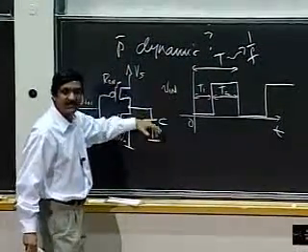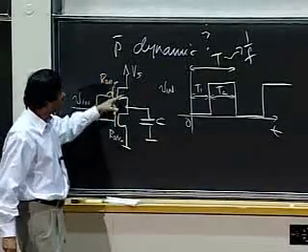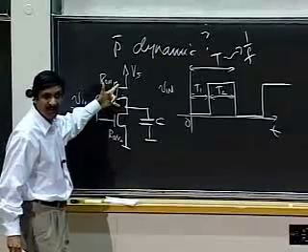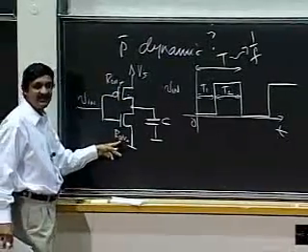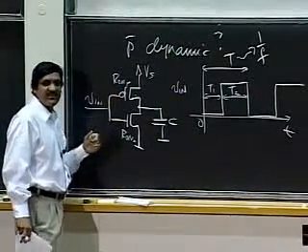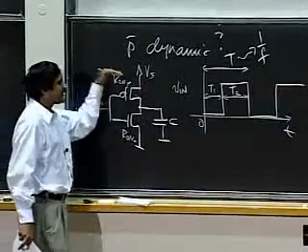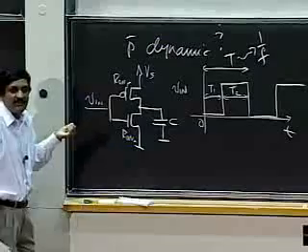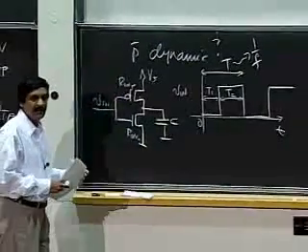me a while to charge up the load capacitor from the load RL. In this situation, RL has now become really, really small. It's R on P, roughly the same magnitude as R on N. So if both of these on resistances are more or less equal and small, then the rise time will be of the same order of magnitude as the fall time, which makes us much faster than the NMOS.